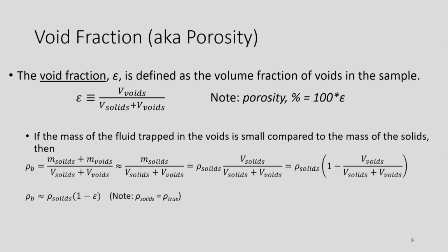Using the mass of solids and volume of solids, you can relate to the bulk density and the solid density of the material. If you know the void spaces and the bulk density, you can calculate the solid density or vice versa. If you know the solid density and the volume of the voids, you can calculate the bulk density. You would all have known this relationship, calculating porosity from bulk density and solid density. Very commonly we use it, right? Yes or no, Ankur? Yes, okay.